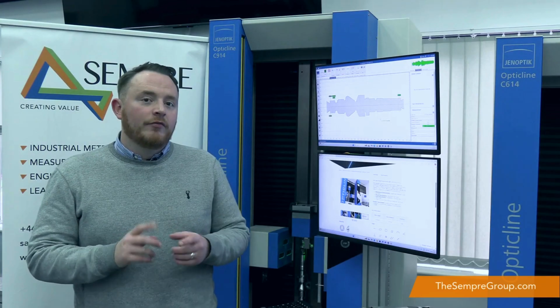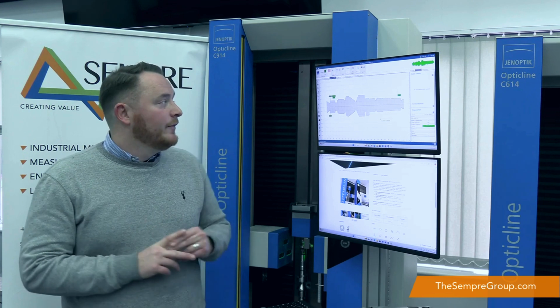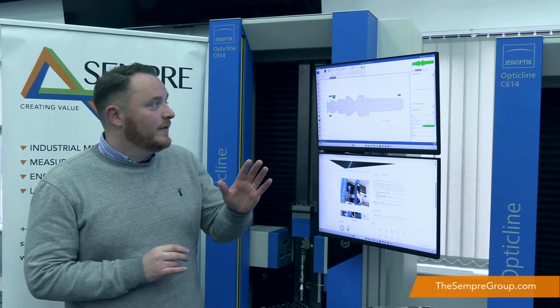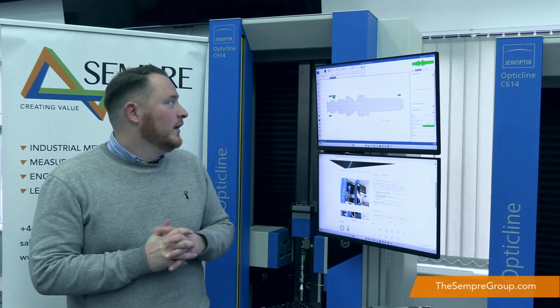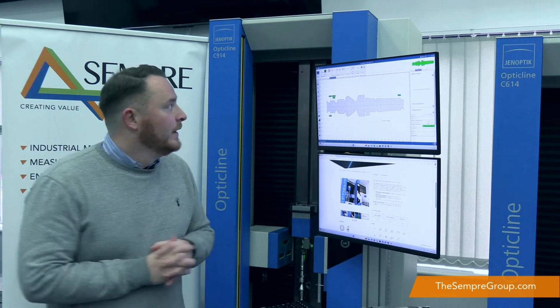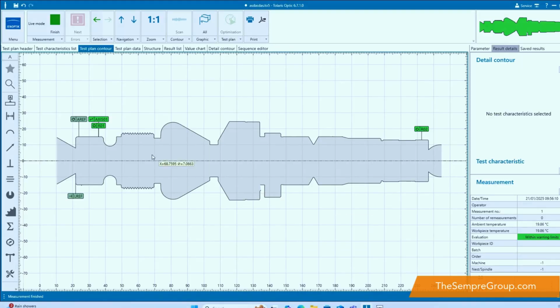So now we're going to take a look at radius and chamfer features. So on the component there's lots of chamfers, angles and radii, so we're just going to take a look at some of the more challenging ones to measure and show you the basic principles on how we can do that. So going to the software, I've got the program set up with our previous roundness plots and the axis, and then I've got my length position, which is our LREF down on this left hand corner.